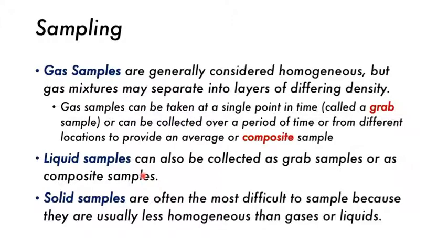So they grab the samples from each road, then combine them all together and measure them. If the composite sample doesn't have very much lead in it, that's good, and they don't need to do anything more. But if the composite sample has significant quantities of lead, then they need to go back and measure each one of the grab samples to find out which road the lead is originating from, which road maybe has the oldest pipes, and those should be marked for replacement.